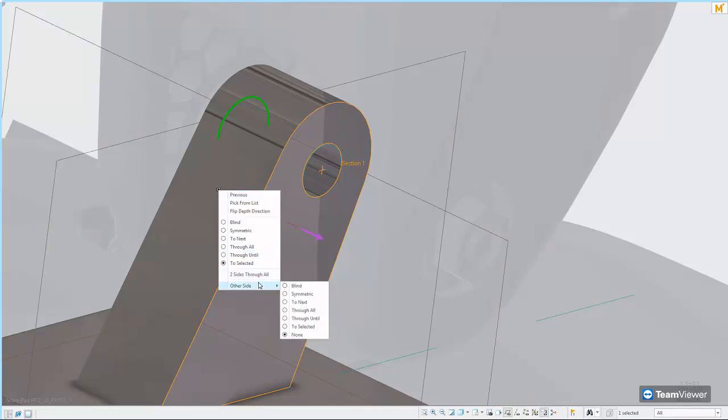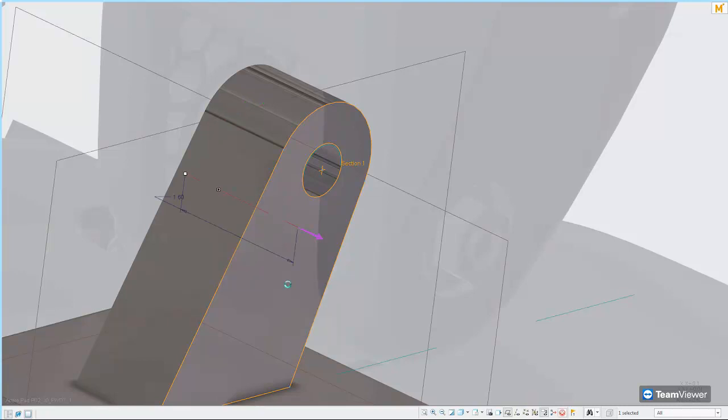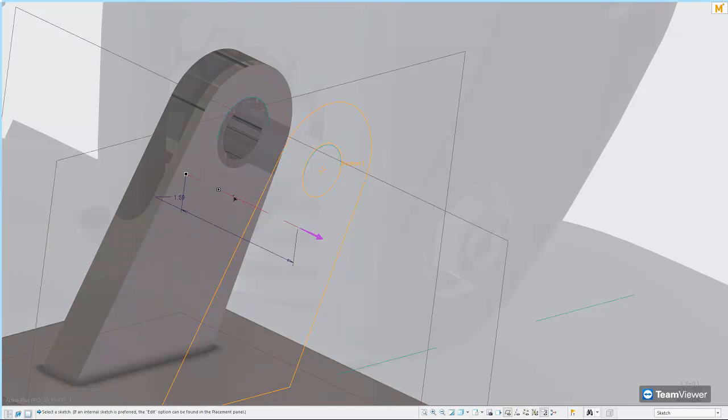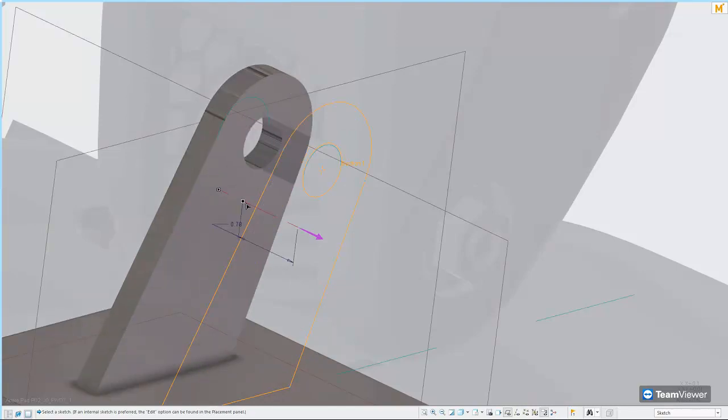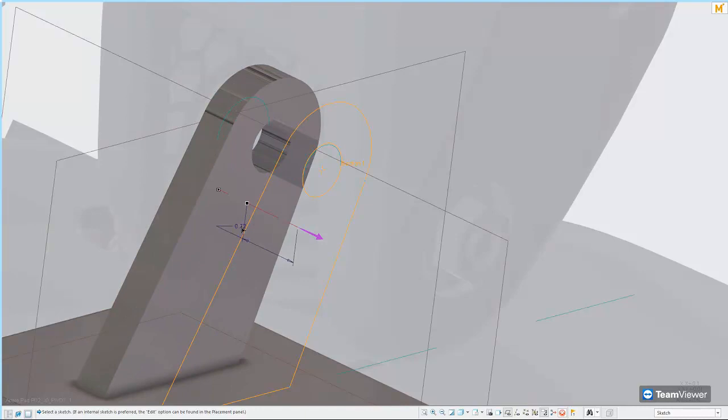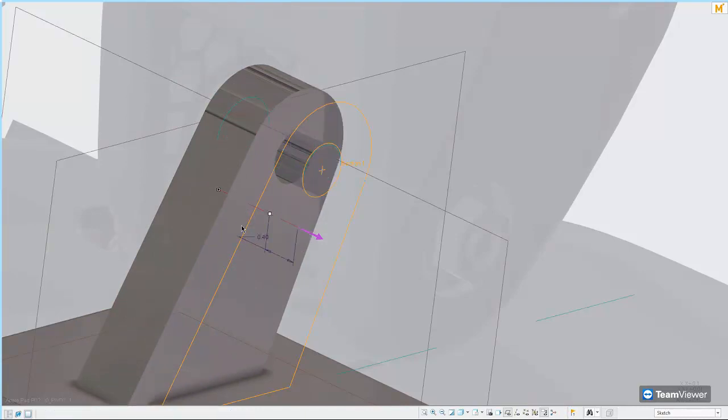So this is very powerful, particularly when you need to create a datum plane or an additional feature to do the sketch. So here I'm going to offset that same extrude, but in the same direction. This is both adding and subtracting material at the same time, meaning I don't need to create additional features, i.e. an additional datum plane in this case, for me to create that feature. It is offset. If I say OK.